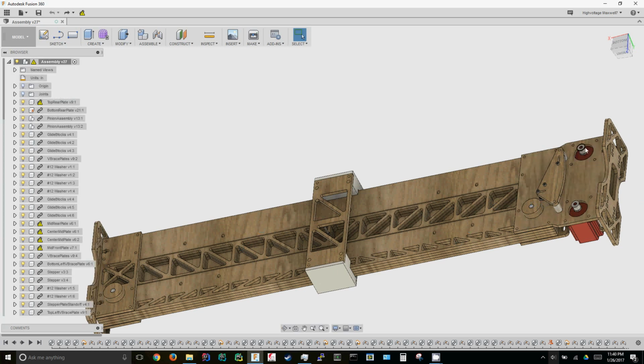The one for driving the needle, the big needle slide in the middle, the one that's vertical, is this stepper on top, and this one just simply goes up across a little bearing there. It's going to go to another one at the other end. I need to model that real quick, but it comes back down and gets clamped onto the UHMW block. I believe at this moment I'm probably going to go with UHMW, or some other similar plastic, but that's just what I'm leaning towards right now. It would bolt to that and then come back around, so this would just pull it back and forth.